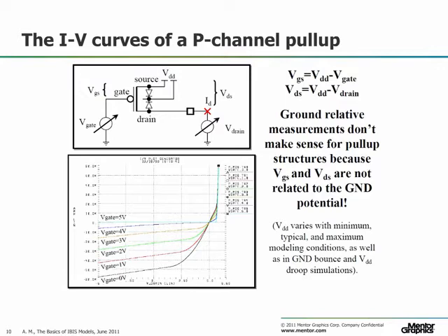It doesn't make physical sense to do it this way either, because a pull-up transistor is connected to the top supply rail, and all of its characteristics depend on the voltages with respect to the supply rail and not with respect to ground. An additional complication arises from the fact that IBIS models are usually generated with 3 different supply voltages for typical, minimum, and maximum operating conditions.